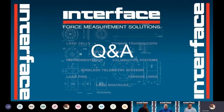And you could say, okay, it's 400,000 because there's 4 sensors, but you'd want to back off of that for safety factor. So the advantage really is that you can allow very large moments because you have a large plate, and then the reaction points are off the center line by as much as you need. So you start to react very large moments without killing the sensors.